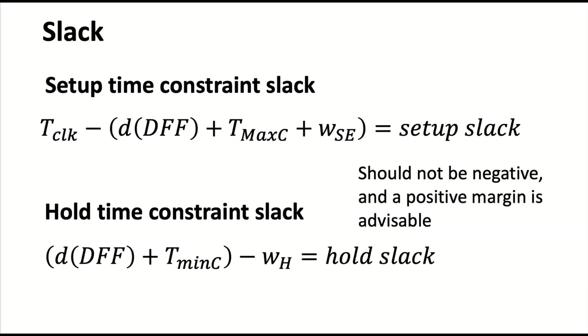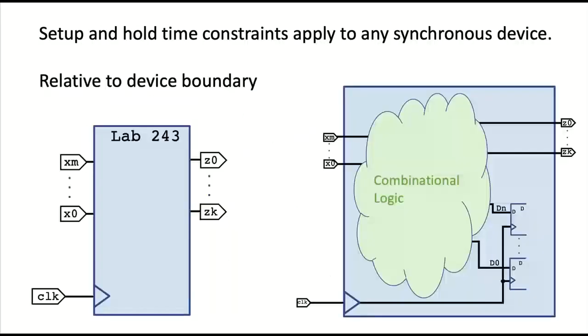So we've been talking about flip-flops, but you can also talk about hold time and setup time of just an arbitrary component. If I have some component here and it has a clock input, and I tell you this is a hold time and a setup time, we're talking about with respect to when the clock arrives at the component.